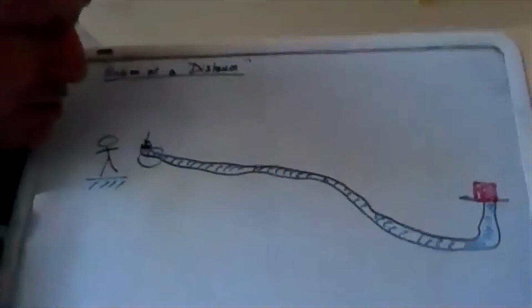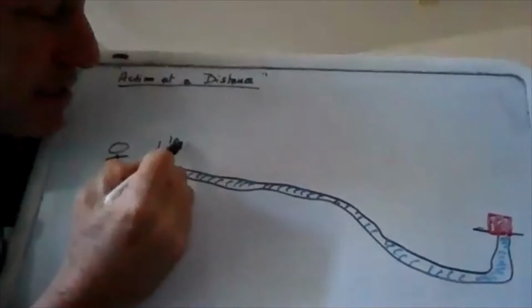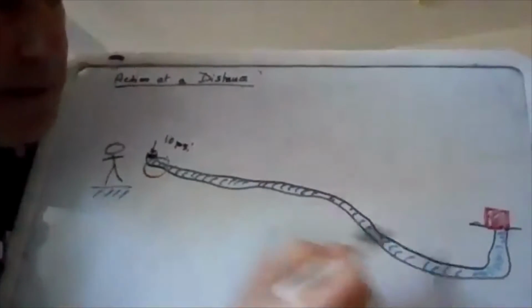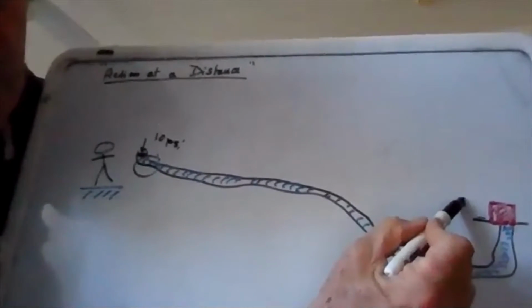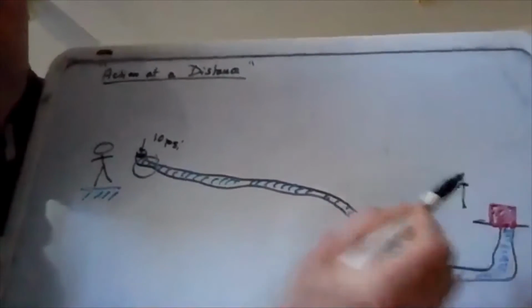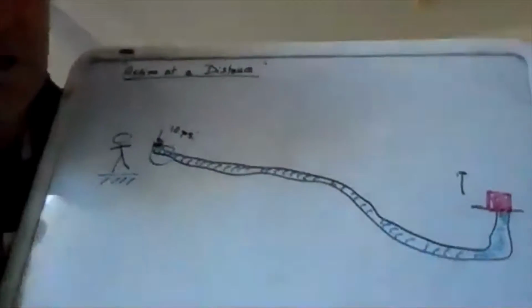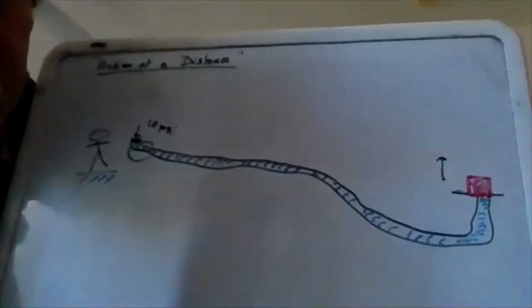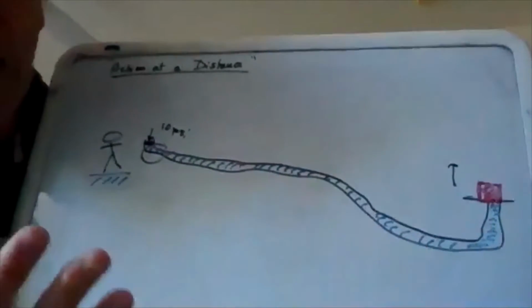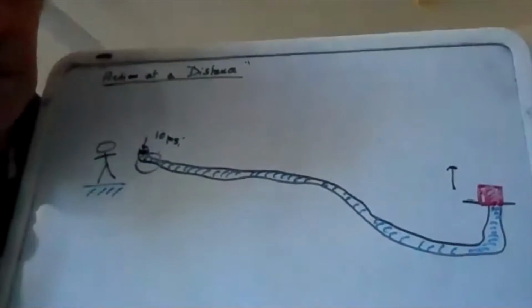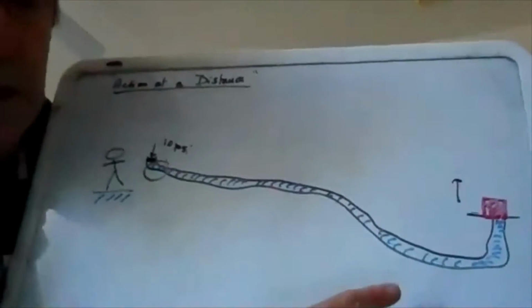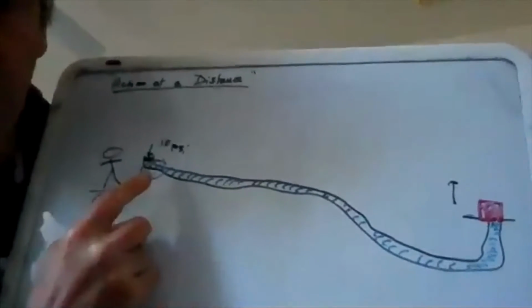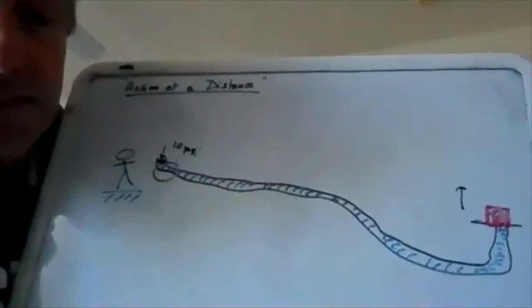That's the key word. So if you exert 10 psi over here on this piston, that 10 psi is going to travel over here to this piston, and that pressure then is going to raise this object over there. So action at a distance, there are all sorts of hydraulic systems. Hydraulics is a word for basically enclosed fluids, where we run tubing and create a force somewhere else by using a force at a distant point.